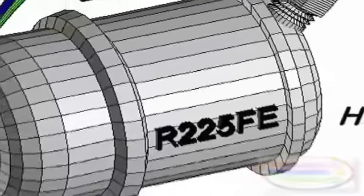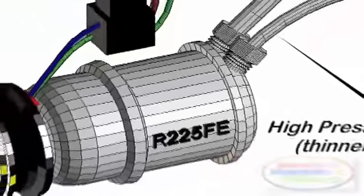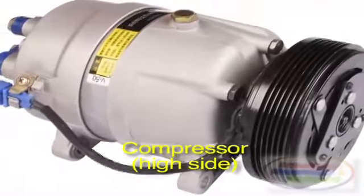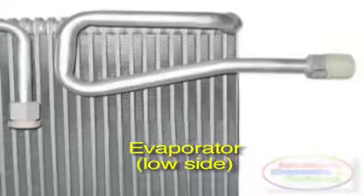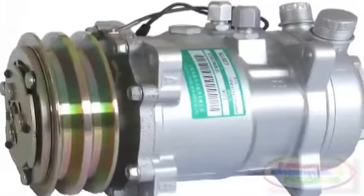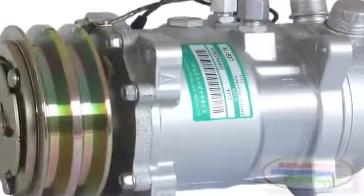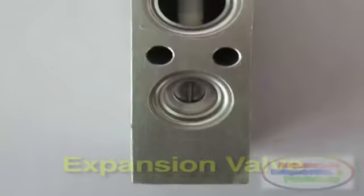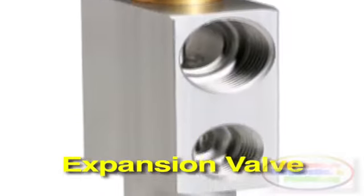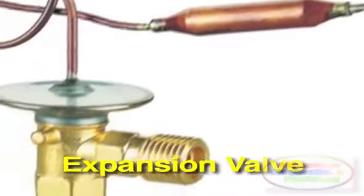The HVAC system can also be categorized into two sides, the high pressure and low pressure sides. The two sides are important because whatever issues are present with the AC system will reflect on the high and low pressure sides. The high pressure side is the direct output from the compressor, and the pressure here will rise if there are issues with the expansion valve or orifice tube, at the condenser or AC cooling fans, an overcharged system, or the wrong refrigerant being used.